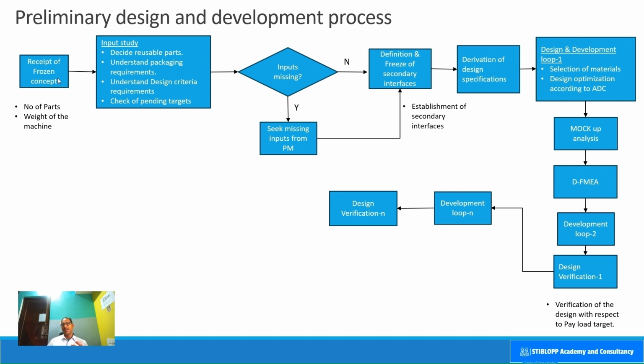They divide your model into a finite number of elements and analyze each element with respect to static analysis, dynamic analysis, frequency modal analysis, and lastly fatigue analysis. All these analyses are carried out, and finally we get the most matured 3D model of the preliminary design and development.